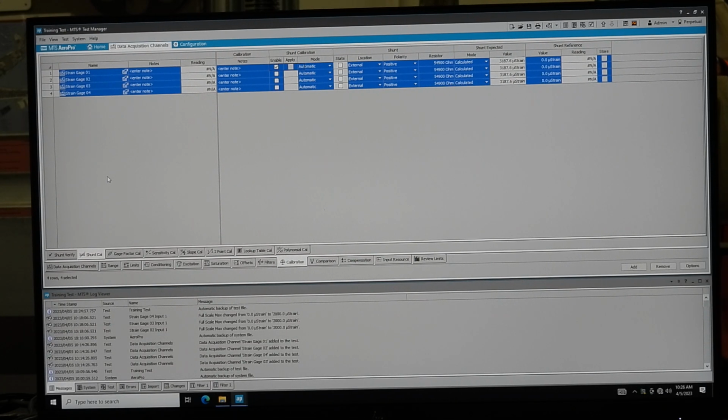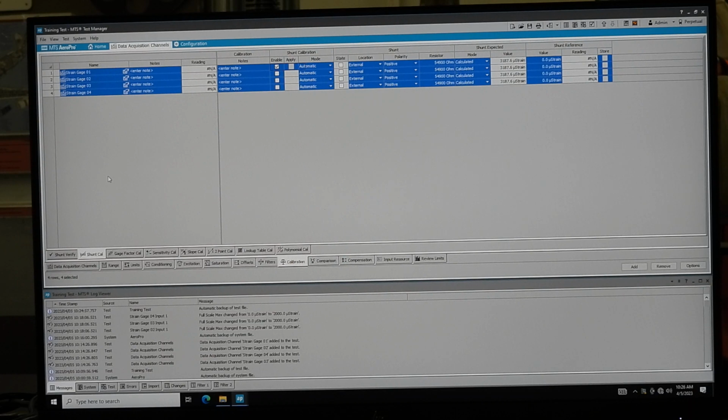You can check what your shunts are compared to 3 months ago when that reference was recorded. So shunt verify is just saying shunt and look at what value I have currently, compare it to the reference from 3 months ago, but don't necessarily change the gains, because the gain may not need to be changed if I'm already within a happy tolerance value to that shunt reference.